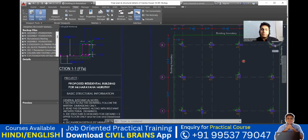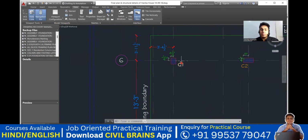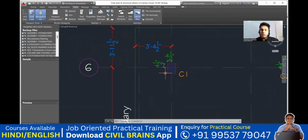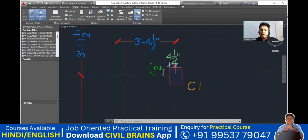Now, like we had it for the footing, in the same way for the column also we have names like C1, C2, C3, C4, and so on. Now you see it here. So again, I have a column here. The name of the column is C1. And what is the size of that? Here they haven't mentioned the overall size. Whatever you can see is 4.5 inch.